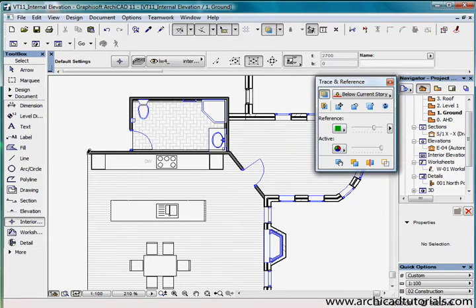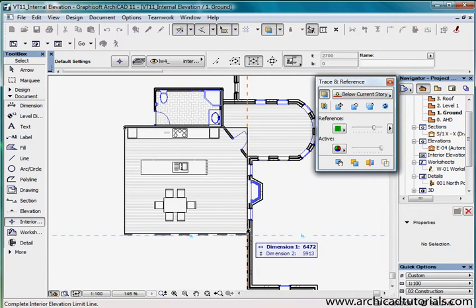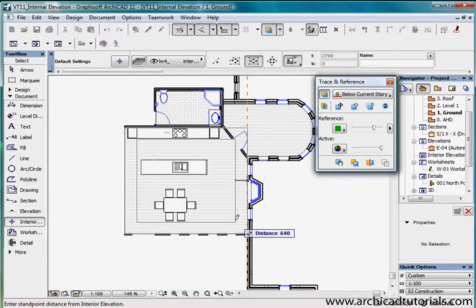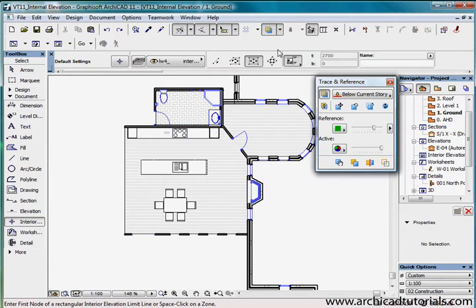If I was to use this one, I just drag out a rectangle similar to a slab, and I'm clicking on the back part, or the rear of the elevation that I want to see. Then I'm going to drag in and draw and click again, and that will place my elevations. If I left mouse click in the project navigator, we can see I have my 4 elevations there. So I'm just going to press Control Z and undo that, and then this one here is a rotated rectangle, where we can draw a rotated rectangle first and do the same thing coming back in the other way. So I'm just going to undo that as well.